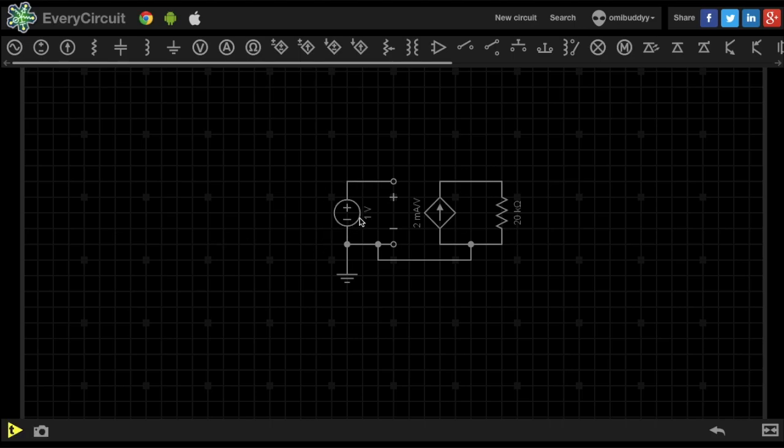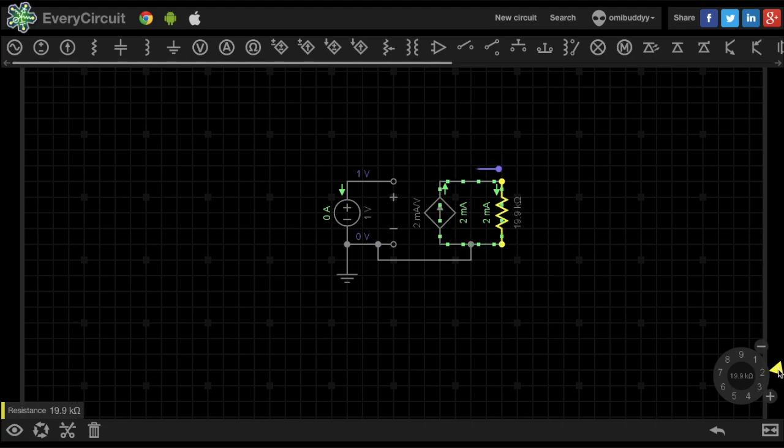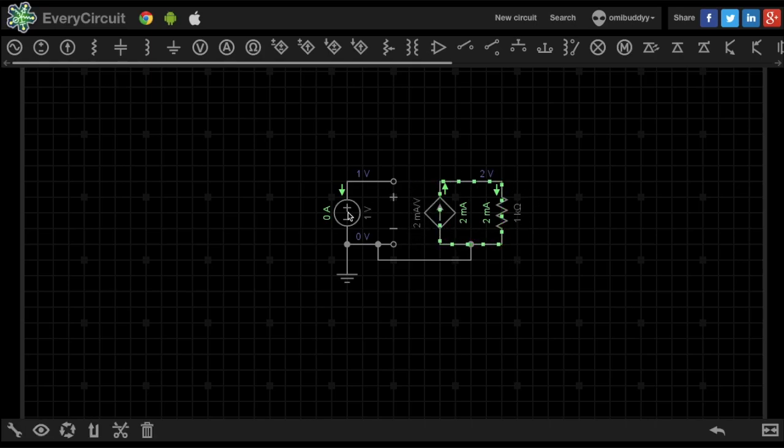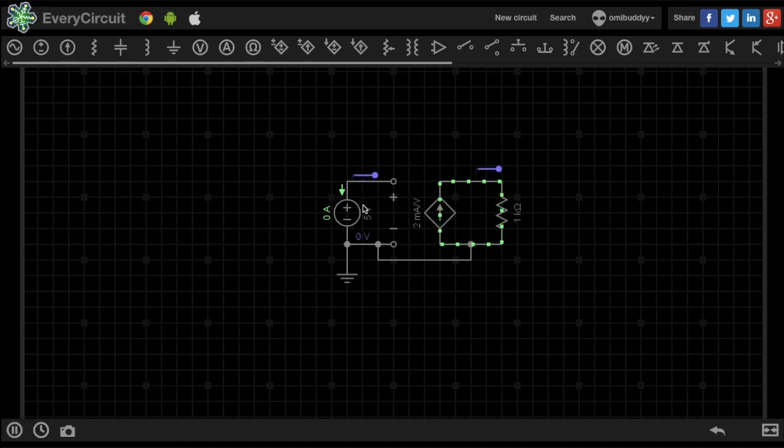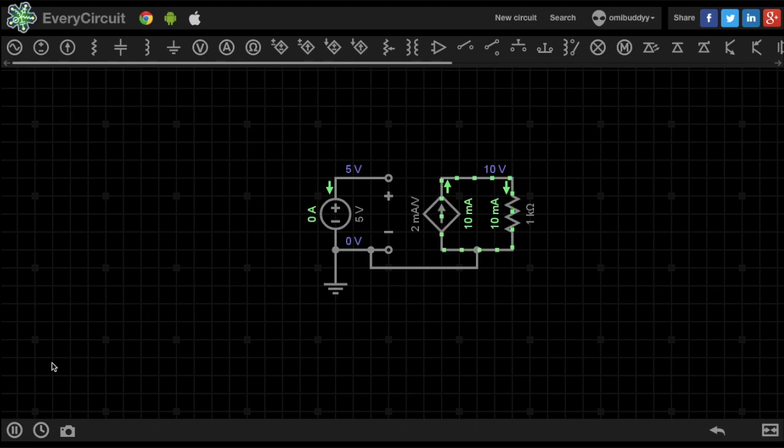As you can see, we are able to achieve gain out of this. If you notice, the VCCS also has a gain factor, which is nothing but the ratio of output current to the input voltage provided. So in this case, we need to change the load resistance value to get the required gain of 2. This shows that if we use a voltage controlled current source, the overall gain will depend on the gain of the voltage controlled current source and also the value of the load resistance. This can be considered an advantage over the use of a VCVS, because we get two variables here with which we can set gain. In the voltage controlled voltage source case, the overall gain was only determined by the gain of the voltage controlled voltage source.